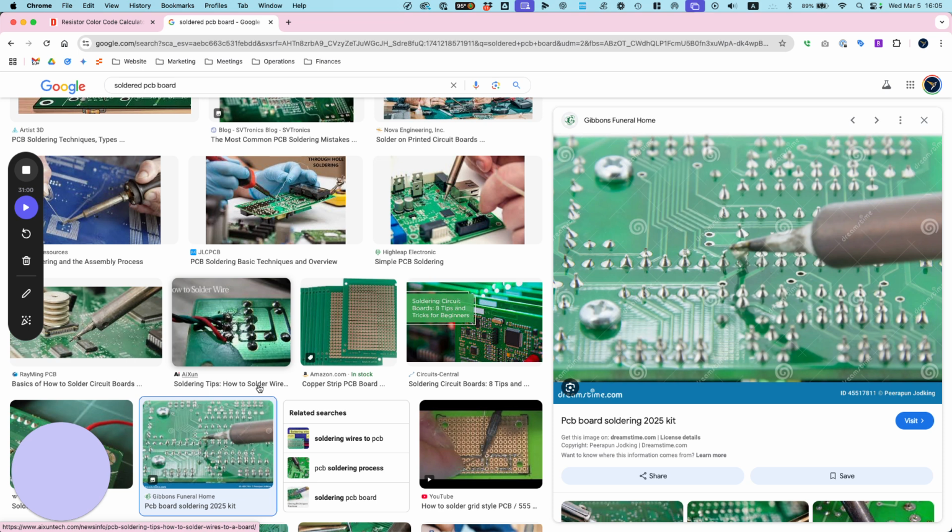So let's build our simple circuit, the one that has this parallel. This is what yours is going to look like on the board, or this is what yours is going to look like with soldering. Okay, I'm going to grab, all right, which one? The short one is the cathode, right? Or the anode? Short one's the cathode. That's going to be our negative. So I'm going to put one end of this into the negative, like this. You see that? It's the short end. The short end goes into the negative rail.